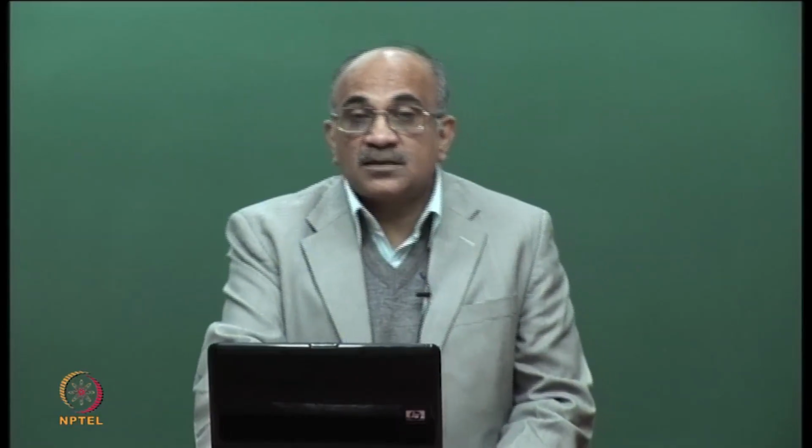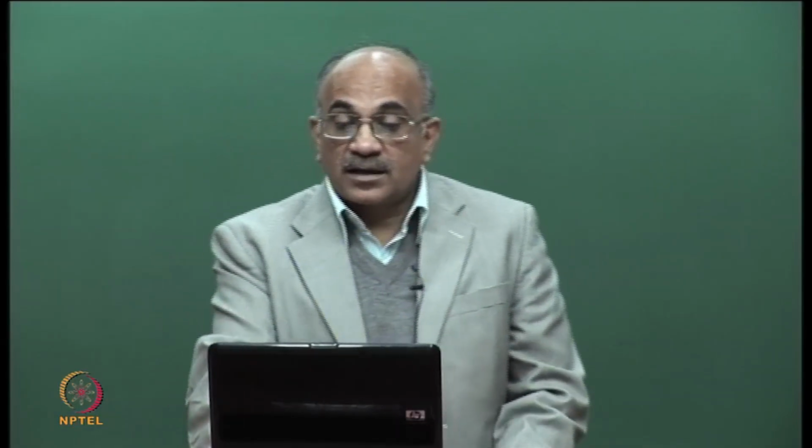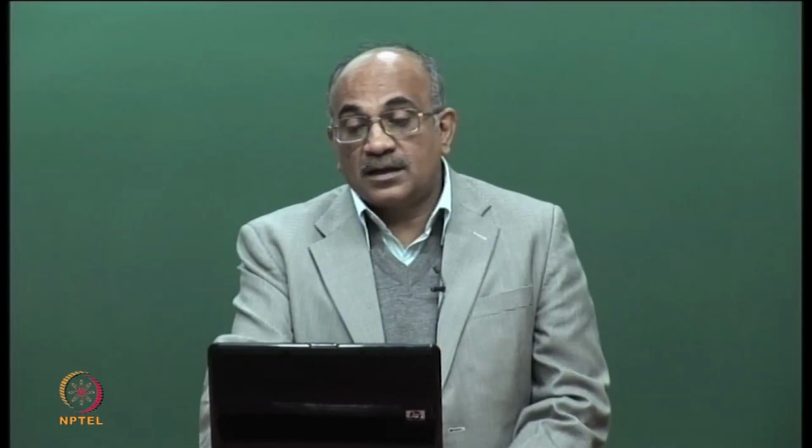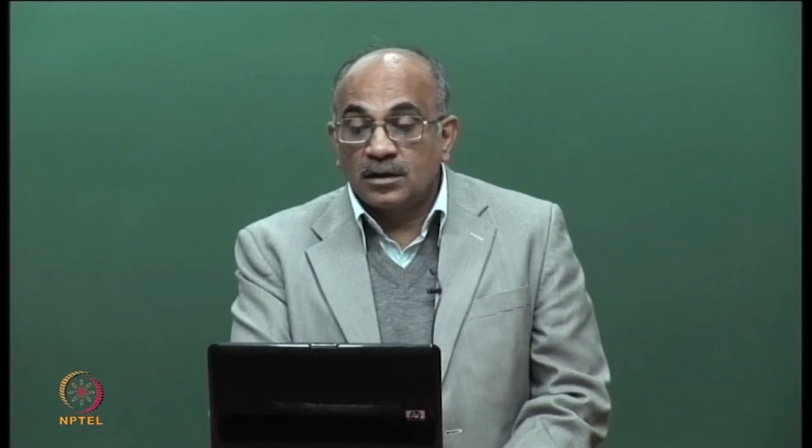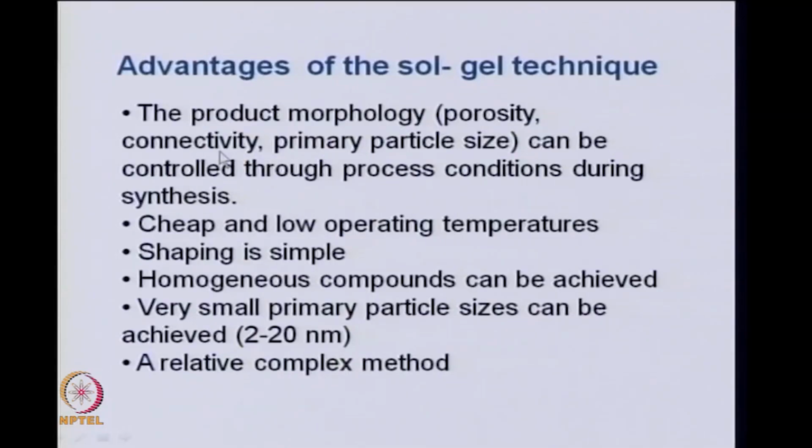The advantages of using this technique are as follows. You have control of the product morphology. So, you can control the porosity, the connectivity, the primary particle size during the processing of the material using the sol gel technique.